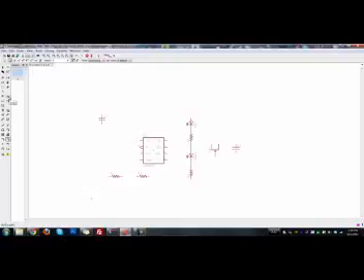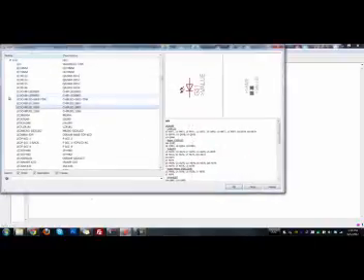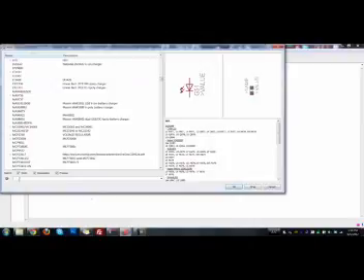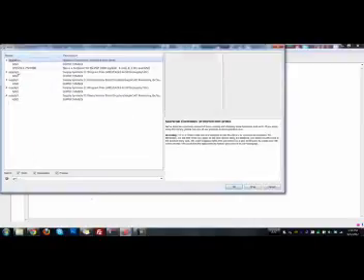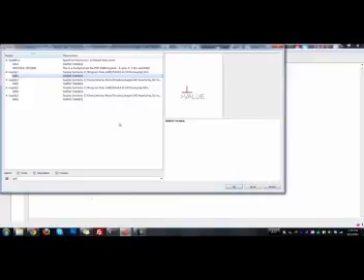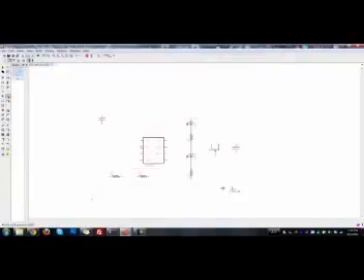To do that, we'll click on Add a Part again, and we're going to be adding a special part called ground. So let's just search for GND in here. It'll come up under Supply. Okay, and just click ground, and we'll add it down here. We're also going to need a ground attached to the bottom of the battery. So just like when you would draw a schematic by hand, you can have two pieces that aren't actually connected to each other, but are still electrically connected. So we'll connect ground to here, and ground to here.